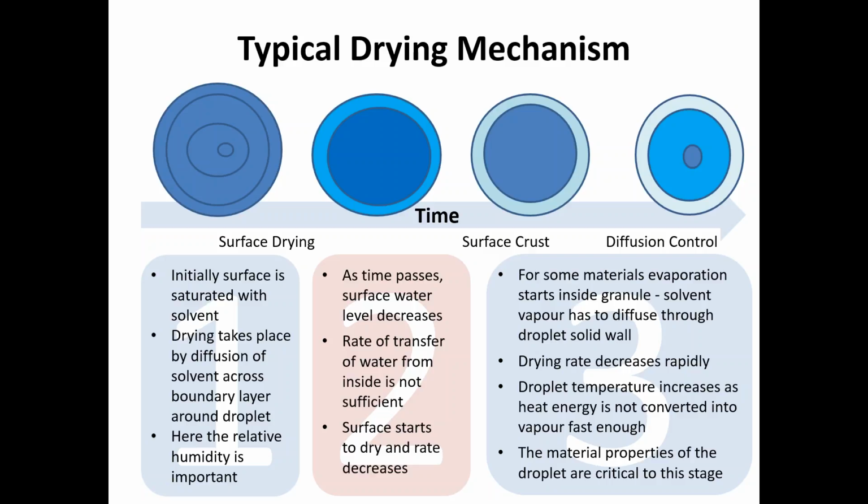This is an advantage for spray drying, particularly for sensitive materials. Much like spraying yourself with water droplets keeps you cool in hot weather, so the evaporation keeps the droplet cool until it starts to lose its speed at which it can evaporate water.